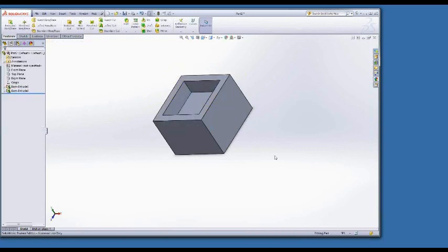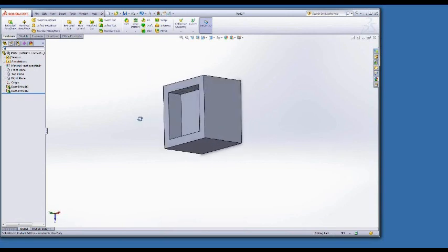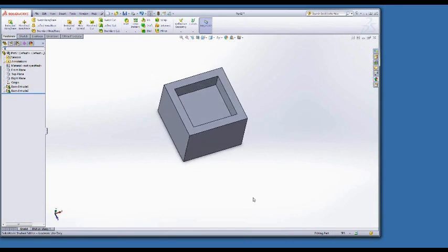And so now what I've done is I have added to my shape with a little 1/8 inch wall, kind of a raised section on the outside. Okay. Done with the extrude command, and the sketch was started with our offset. Okay.